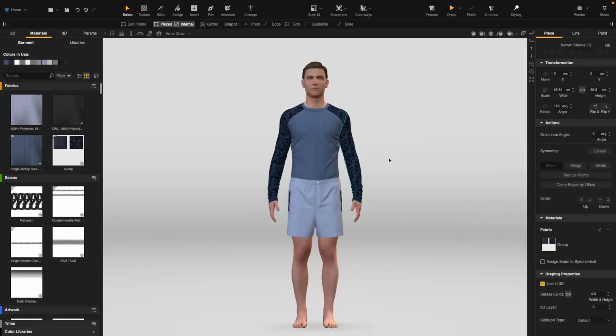When we right-click in the 3D view, some options are displayed. To view the options, we must right-click using the mouse and hold. When we place the cursor on the background, then right-click the mouse and hold, these options are displayed. Show 2D window or Maximize 3D window, Reset view, 3D annotations, Load related avatar, and Edit lights.